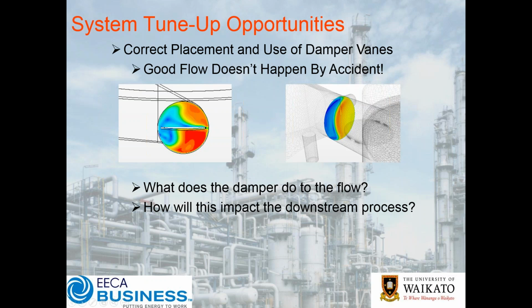Now what of course happens is we probably, to be fair, don't want the butterfly vertical here, because that will segregate the high velocity zone, which is your reds and your yellows in the picture over here, all on this side. So if I just change color here and go with a pen, the last thing we want is the butterfly vertically, because that's going to segregate the flow on one side and not allow it to expand at all.